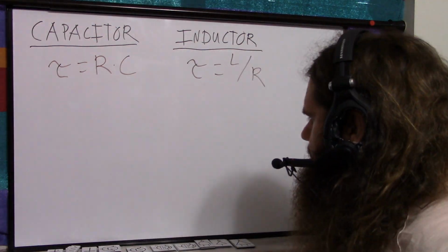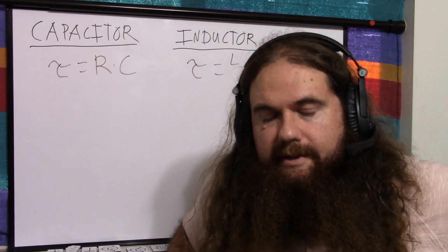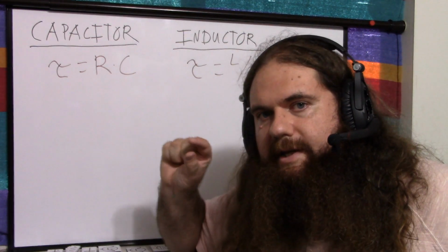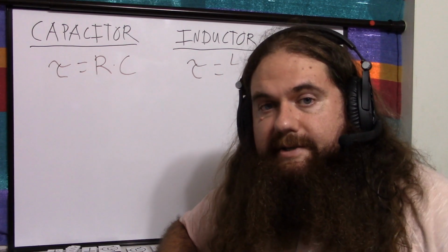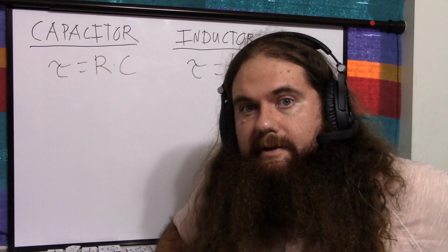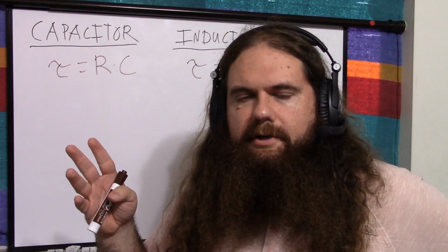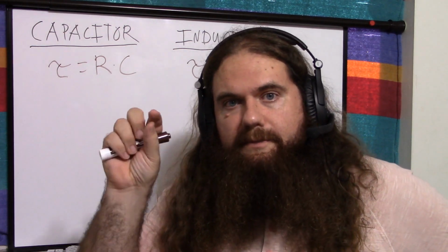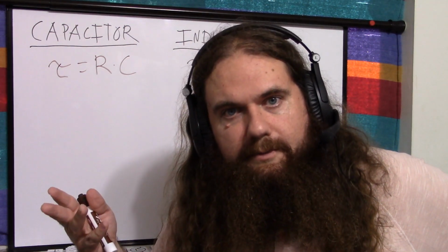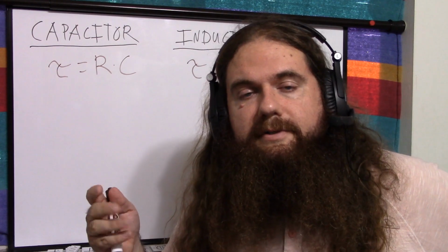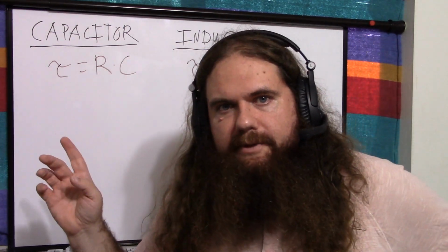Now, you're going to usually find filters made out of capacitors rather than inductors. First of all, because they're easier to understand. Second, because they're more compact. You can get a capacitor a whole lot smaller than you can get an inductor. And third, they're a little better behaved, as evidenced by me hooking up inductors to my oscilloscope. Capacitors give nice, beautiful, easy to grasp voltage curves, and inductors give the correct curves, but the oscilloscope reads them as fairly wiggly and noisy. I'm sure improving the quality of my inductors would help there. I've actually ordered a box of really good ones, because right now I'm using a homemade inductor and it's not perfect, let's just say. But the point is, they're backwards from each other, just like this.